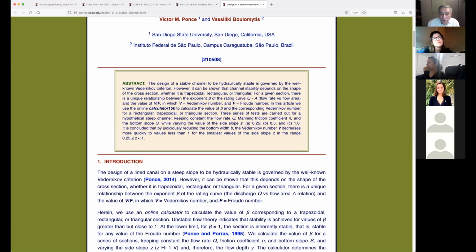So we find out from this practice that the channel is going to have to be trapezoidal, because building a triangular channel, a large triangular channel, is difficult. I don't believe it has been done. So we can do it trapezoidal, but we can do it trapezoidal in such a way that it would look or behave more like triangular than rectangular, because it would be kind of in the middle, more toward one side than the other, right? And that's exactly what we're doing in here.